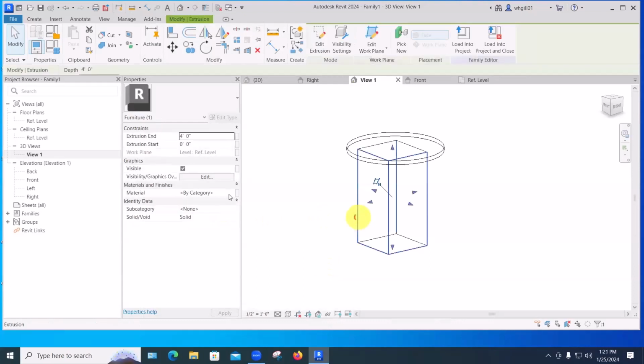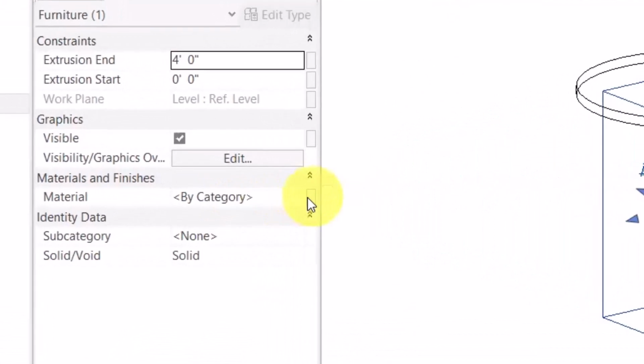What I actually want to do here is create a new parameter, which is like a stand-in name where we can pass information back and forth from the project level back to the object itself. So we're going to go to Material, and over here, this little dot, we associate a family parameter. We're going to click on that.